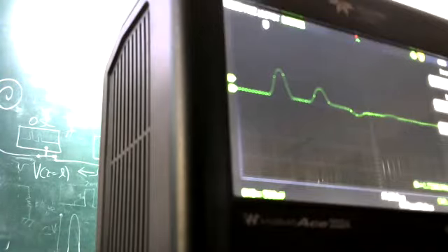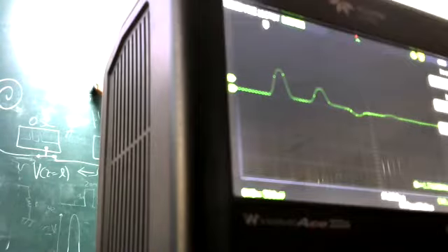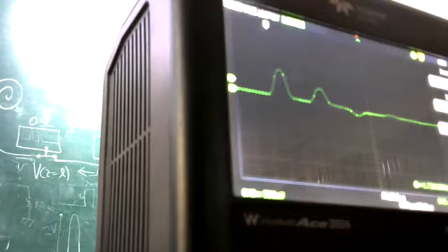What you get is V0 over 3, but this is V0 over 2 into 2/3. It's slightly confusing, but it's just a sequence of operations, right? The true voltage source's amplitude is V0. Nobody ever gets to see that unless you measure in 1 mega ohm. That's what we saw when it was 2 volts. The matched situation, which is basically when this was 50 ohm, we are able to measure. That's 1 volt. That is V0 by 2.